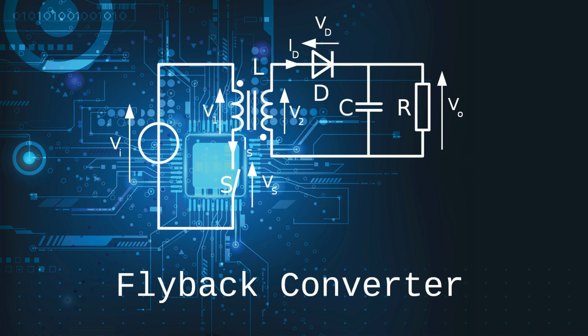Like our buck and boost converters, these flyback converters also have a switch, a diode, a capacitor, and instead of an inductor we have a transformer. That is the only difference, and they are connected in this fashion. Then the switch S will be operated on and off. Power will be transferred from primary to secondary, and the secondary voltage will be rectified to get the DC current. This is the simple way of explaining this operation.